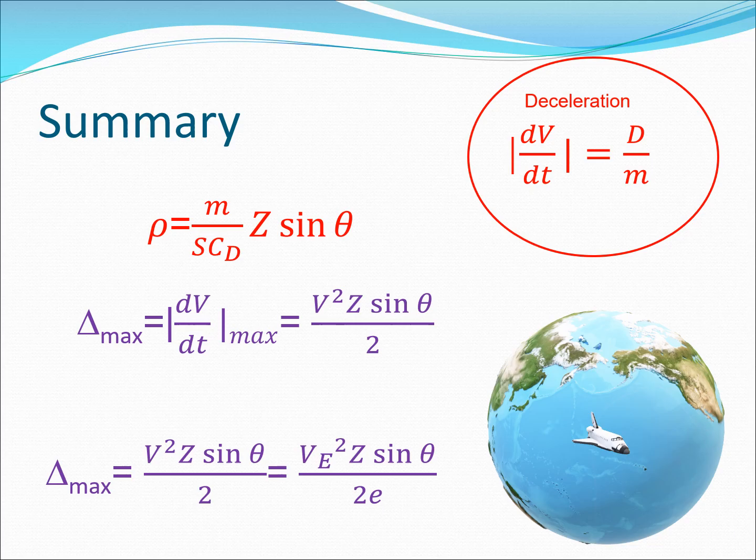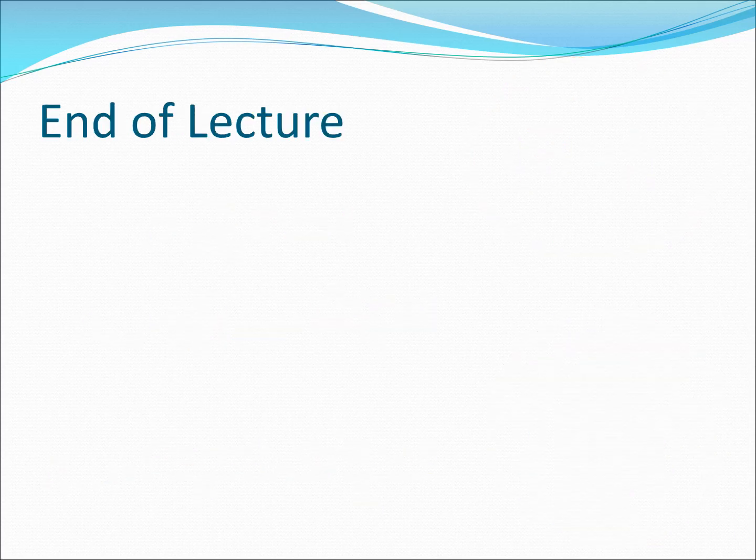Like I mentioned before, that is a useful ingredient in the design process, because here you are taking care of the people who are in the spacecraft in case you have a manned spacecraft. For an unmanned spacecraft, you need to find out what is the exact maximum G which the equipment and the systems can take, and you need to design for that.